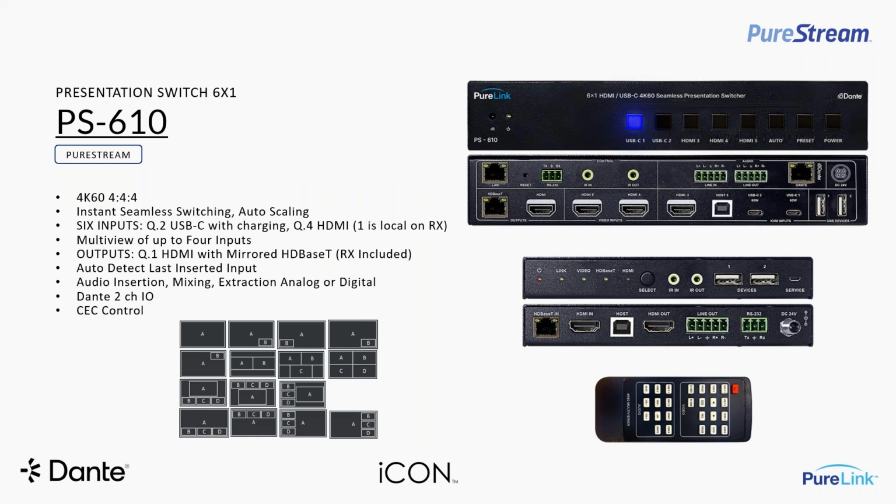And then you've got 3 HDMI inputs on the back of the main switch, HDMI 3, 4, and 5. But you'll notice the HDBaseT receiver below that comes in the price with the product. It connects to the output, which is parallel. So you have HDMI 4K 60 out and HDBaseT 4K 60 out to the receiver. The receiver has a local HDMI input.